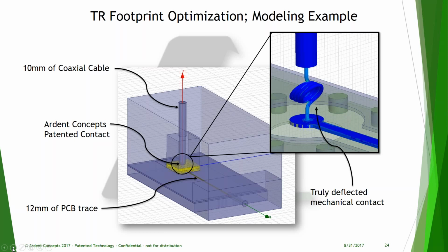It is possible to use the wave port in a strip line configuration, and by possible, I mean physically possible, but again, without the TR device there, you're not going to get those properties that the TR device introduces to the board. And some of those properties, in a nutshell, are that the TR body is metallized, and it grounds itself onto the top layer ground plane. So you have some added capacitance from the TR device that you really won't see unless you include it in the model properly.